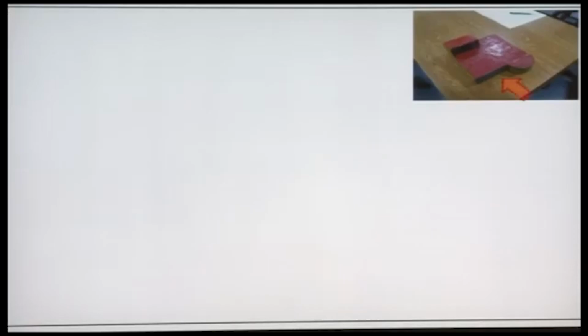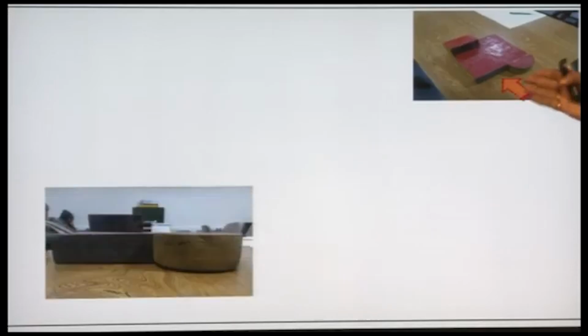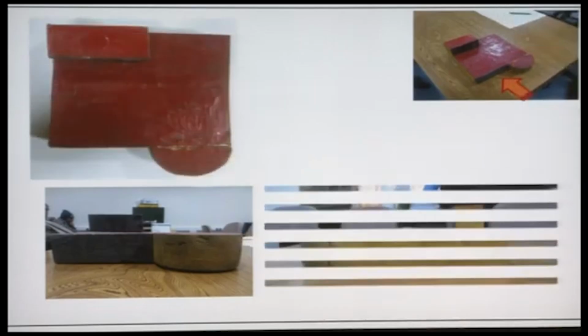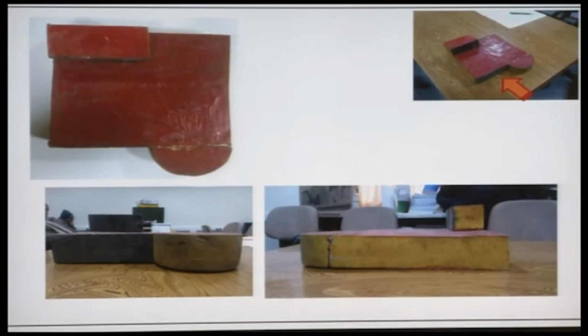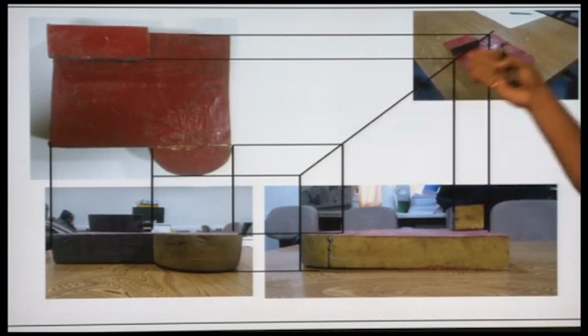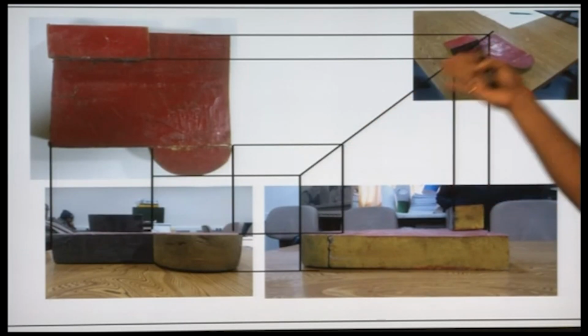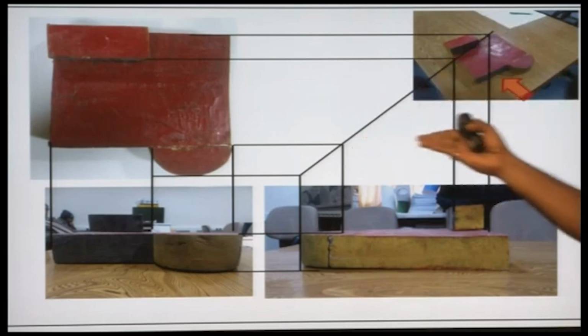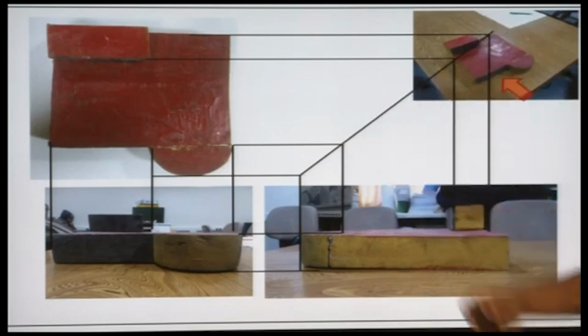Third object, if this is the front view, this is how the object is going to look in the front view, the top view and the right hand side view. If you again correlate different features of the object in three different views, this is how the projection lines are going to look. In every instance, this line will be making a 45-degree angle with the horizontal line.